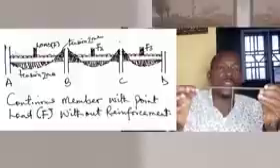Okay, but for this now, the area you're going to have it is, below here, you're going to have your tensile stresses. At the top here, you have another tensile stresses, while somewhere here, you have another tensile stresses. Now, from what I've explained to you, the steel is very good in tensile stresses, and the concrete is good in compressive stresses. So where do we put the steel in this kind of connection?